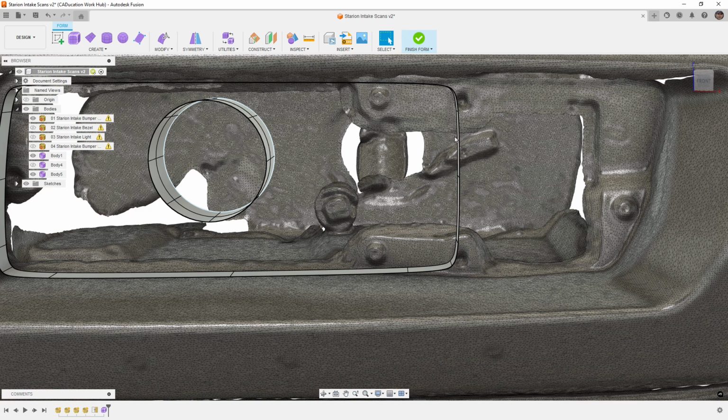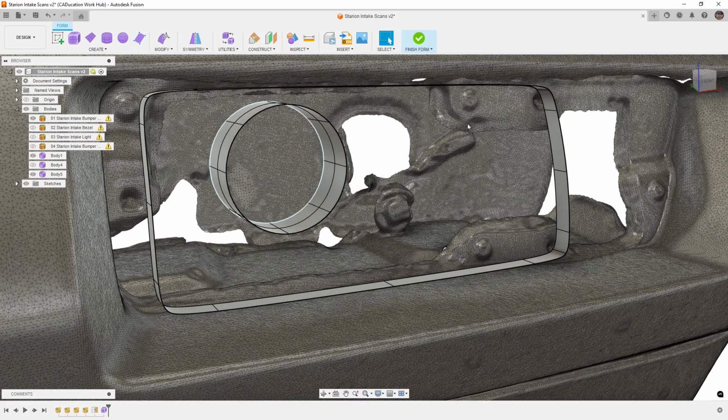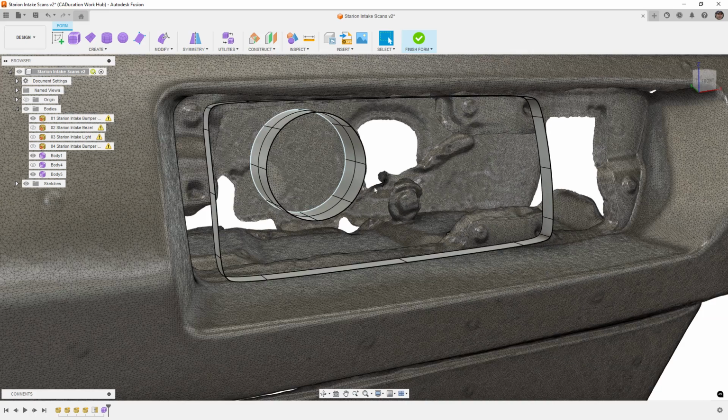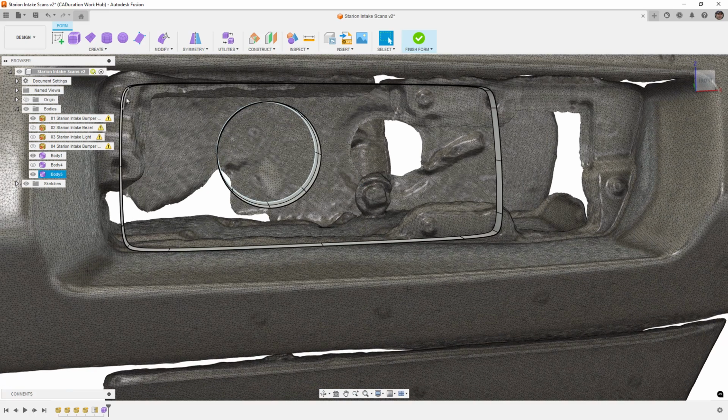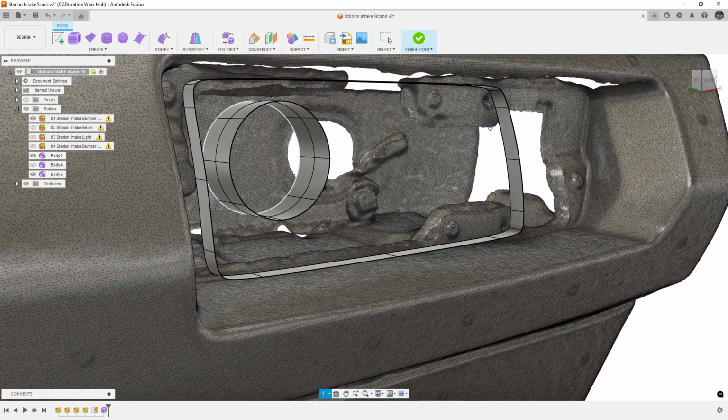So this duct is going to have to transition quickly from here. Now it can go from this section over into that opening there, but up here we don't have any real estate to work with. On this side it's not as bad. We can duct it over quickly, but these are things that, again, we don't want to cut. We're just going to try to work with it.